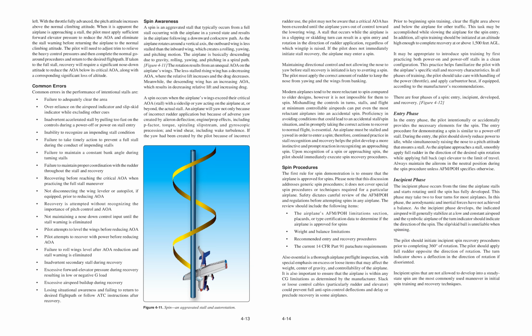Spin awareness. A spin is an aggravated stall that typically occurs from a full stall occurring with the airplane in a yaw state and results in the airplane following a downward corkscrew path.